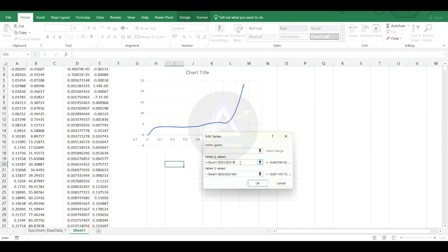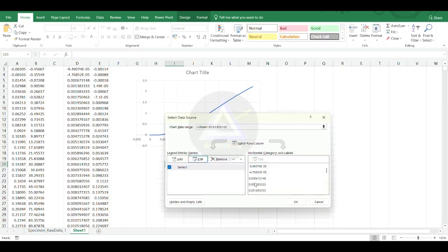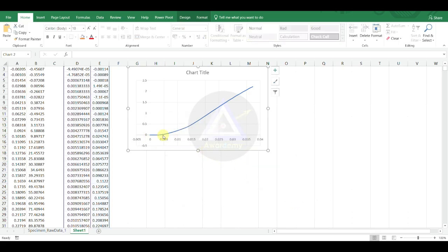Here you can type the values up to 100, as we have the maximum value of 100. Here you can see there is some non-linearity in the given data. So we are trying to remove that particular data, and we are trying to start our values from zero with a linear region. For that we need to evaluate the elastic modulus.